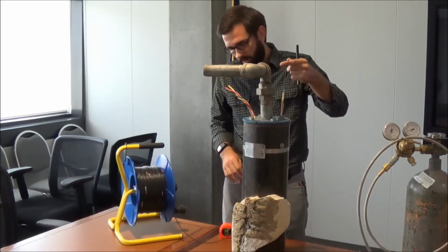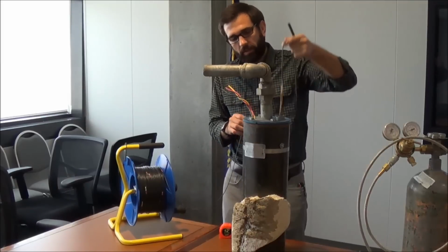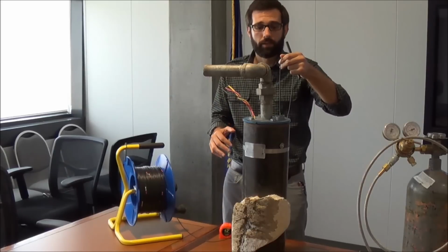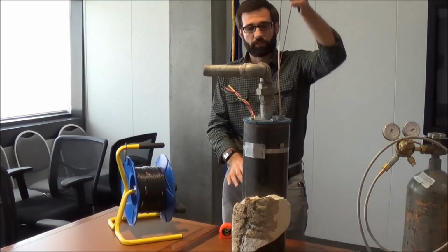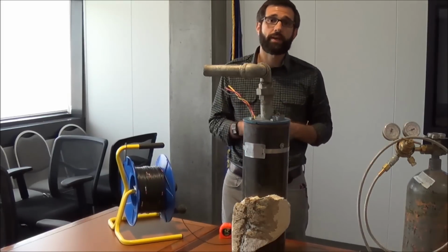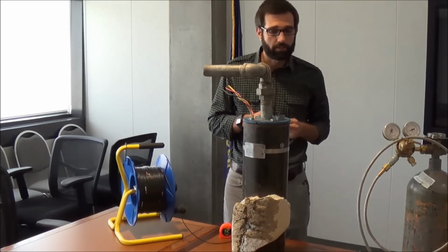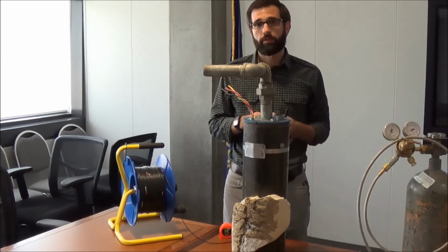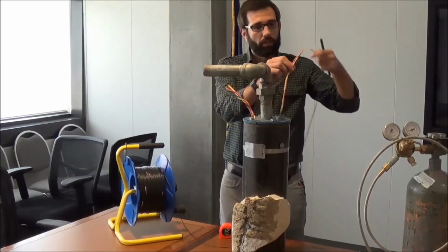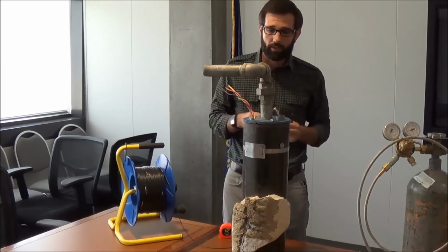If you're hung up, something that we like to do is raise and drop. If you drop quickly past that point, a lot of times you can get by without an issue. So that's just a technique that we like to do. Sometimes you need to add extra weight. You're going down a long way, or there's an obstruction that you can't get by because your line's not heavy enough. So we put a few extra lengths of copper pipe on there, or copper weights.